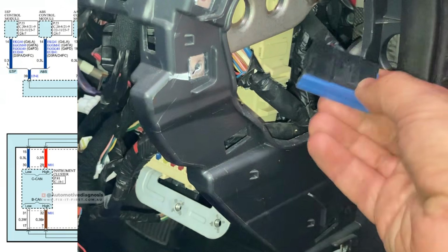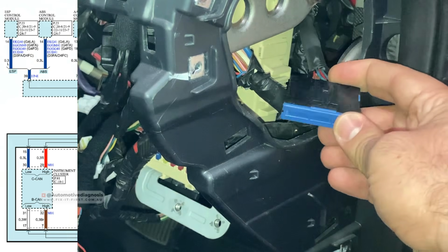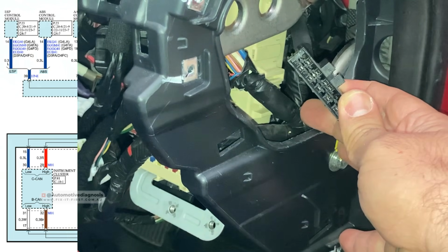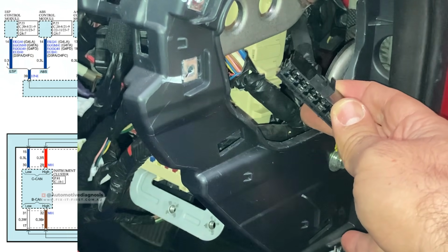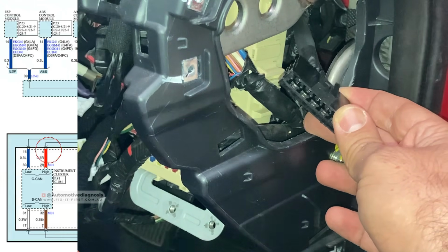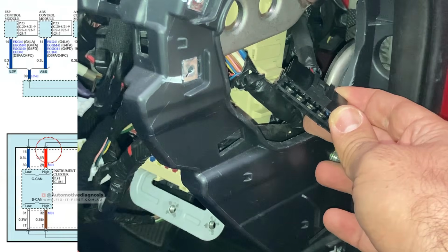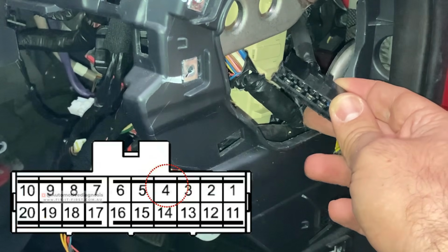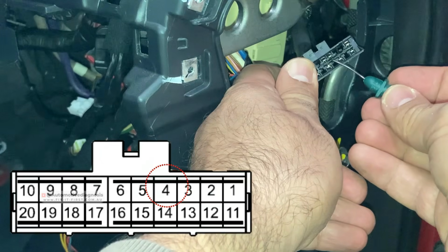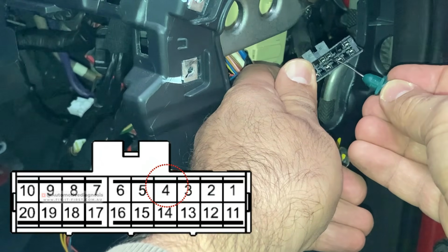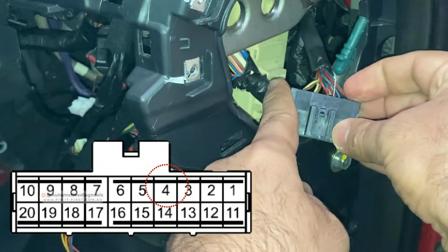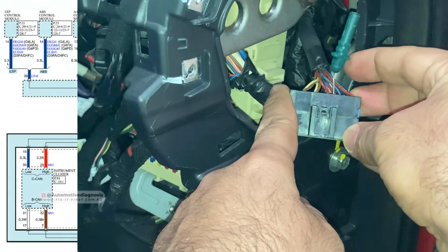Here is the joint connector. You see the wiring diagram at the same time on the screen. So I'm going to take the joint connector out again. On this side, we can of course check the CAN high and CAN low. If we focus on the CAN high, pin number 4 on the joint connector is for the CAN high of the instrument cluster. So look at the joint connector details. You see the pin number 4. This is actually pin number 4, which is the CAN high for instrument cluster. This red one, I can insert the test probe from there. So this is for the instrument cluster CAN high.